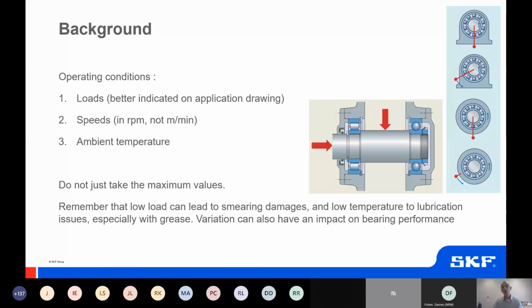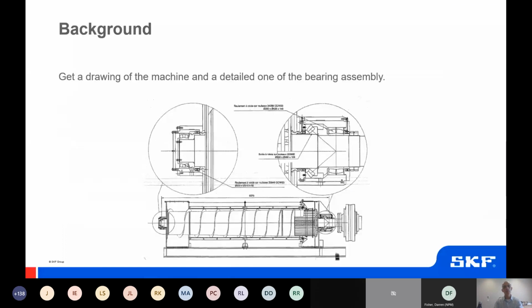Is it a bearing running at low speed or high speed? A typical question or discussion is whether the bearing was running hot. Is that enough? Or we need to understand if the bearing was running hot as a consequence of the failure or was running hot because it's part of a process. So we need to put the situation in context so we can help the analyst, again, if you are sending this to somebody else, to understand the conditions and the context under which we are making statements.